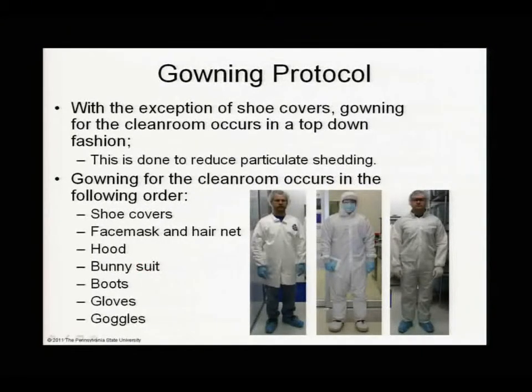On the gowning protocol, just to go over that, this is a very simple type of gowning situation. Perhaps you're working with a workstation and the samples never come out into the environment. This is a more stringent clean room attire, and this would be used in a higher class clean room. This would be used in a lower class clean room, maybe a class 100,000.